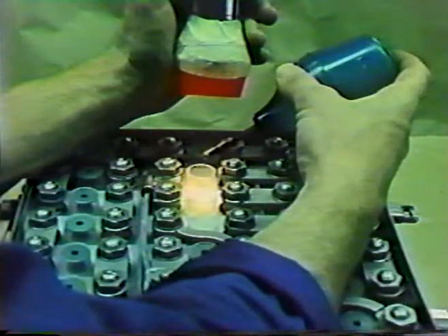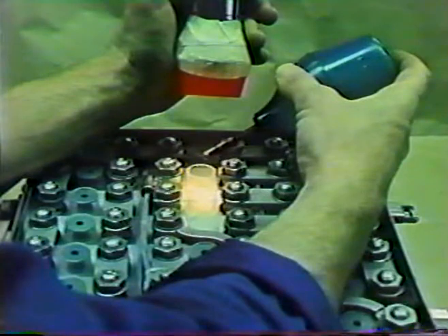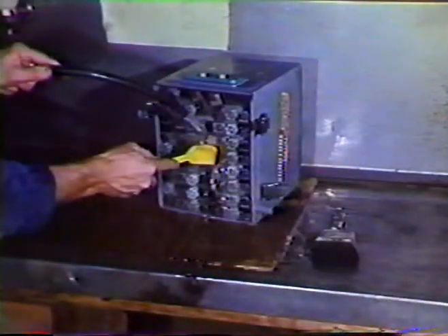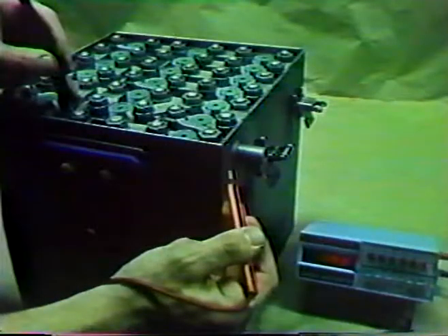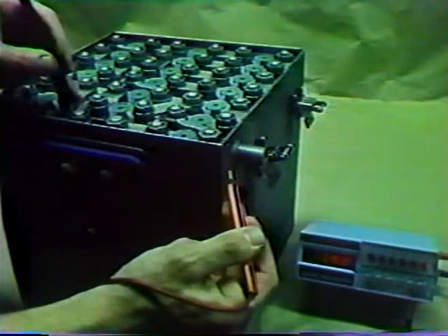Adjustment of electrolyte levels should be done only in the shop where the condition of charge of the battery may be determined. A typical shop service sequence consists of scrubbing the battery with a non-metallic brush and boric acid solution, then rinsing with tap water and air drying. Check for current leakage between the cells and the case. More than 100 milliamperes is excessive, and the battery should be disassembled and cleaned.